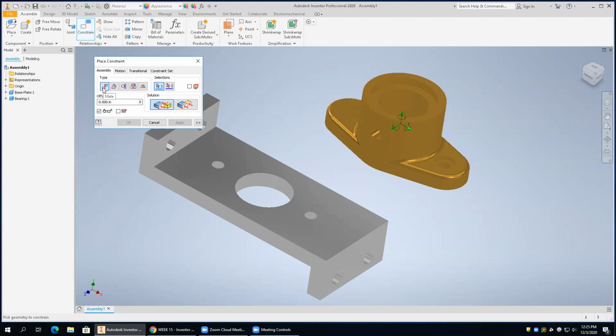This guy right here is called a mate constraint. So I can bring 2 surfaces together, like that. Now, I can not only bring them together, but I can have an offset. So they can be together, but there'll always be an offset. The one can ride above the other one always, but it's always at a fixed distance. So they can either physically touch or not touch, but if the parent moves, the child's going to move with it the same way. You guys get the idea?